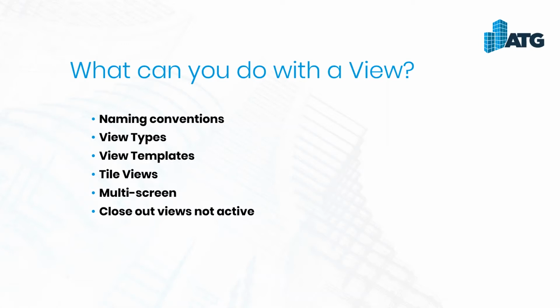quick access toolbar, you have an option to close out the inactive views. Remember, it doesn't close out of your project. It doesn't get rid of any of the changes that you've made in any of those views. As long as you have one view open in your project, everything is stored within that project. So when you save it, it will save everything within there.